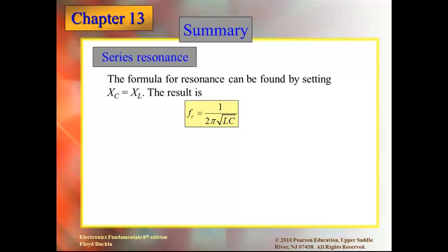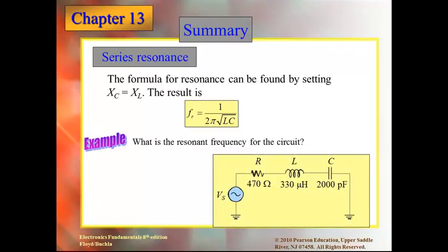to the circuit. And like we said before, resonant frequency can be calculated with 1 over 2 times pi times the square root of L times C. So here again, if we know the inductance and we know the resonant frequency, which we happen to know again is 60 hertz, we can figure out how much capacitance there should be in the circuit. So we're going to use these formulas a little bit differently nowadays.